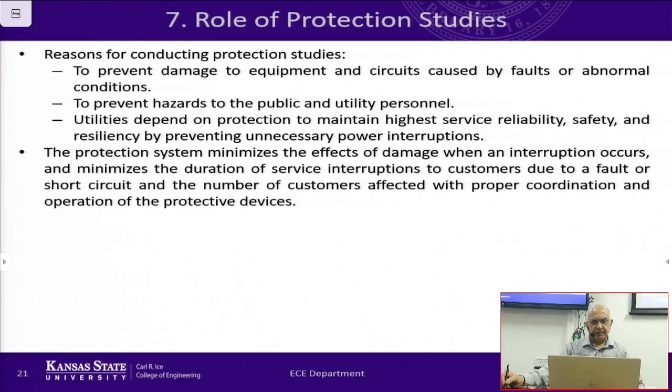And if you design protection properly, then it will minimize the effects of damage when an interruption occurs, and minimize the duration of service interruption to the customers. So the goal is to isolate as little of the system as possible, and then try to restore whatever else can be restored as quickly as possible.